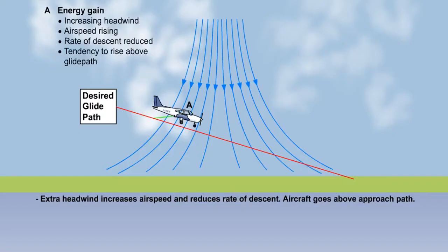If the speed increases suddenly, resist the temptation to decrease power, as the effect will probably be short-lived and will probably be followed by an opposite effect. It would be better to disregard the glide path and raise the nose to control any excessive speed.